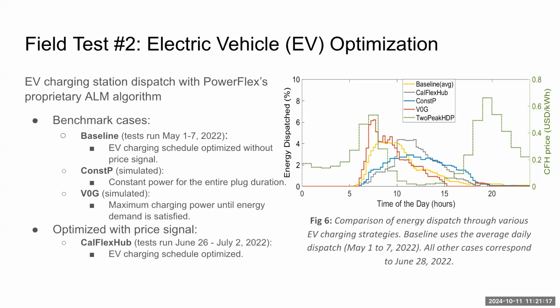Communications, the other question, was about communications with the vehicles. We actually only communicate with the charging stations. We do not communicate with the vehicles. That's right now basically the standard. We do not yet have the ISO 15118 standard, which would allow communication between a vehicle and a charging station. It's currently essentially non-existent, but hopefully very close to being rolled out more widely. So it's easy: you just communicate with the charging station. That communication is already in place because you have to charge the user, so you are able to read what the charging station does. And that worked quite reliably.